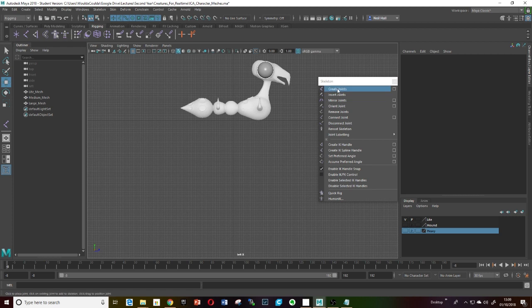So you can click on create joints, or you can use the create joint button up at the top here. You must be in an orthographic view to make this easier to do. You can do it in perspective if you want to, and it will drop all of the pivot points on the ground plane as you work, but it makes sense to actually see the object from front or back or side or whatever.